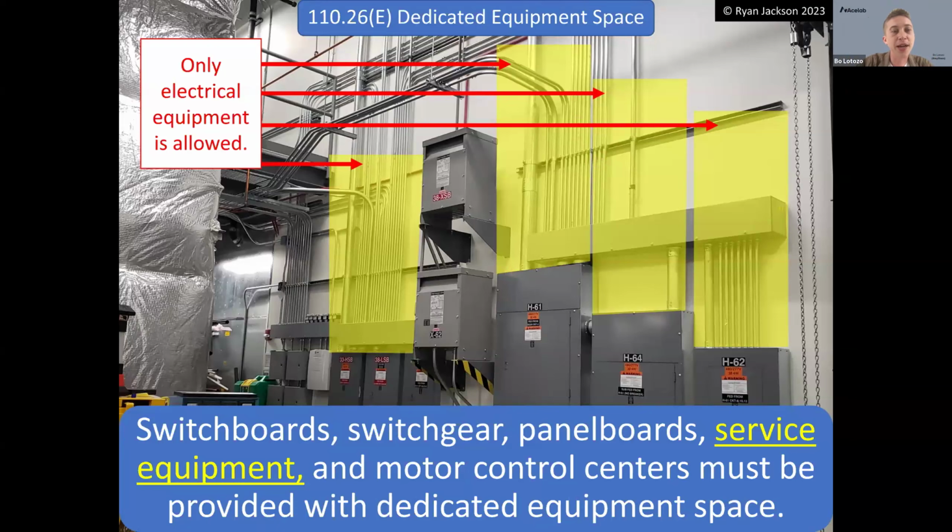All right. So Brian asks, what was discovered to be the culprit of the low voltage event shown in the early slide? Yeah, great question, Brian. So that was a low voltage lighting system, it was not what we would call Class 2, which is very, very low voltage. This was one of those lighting systems you sometimes see in restaurants where it has the 2 conductors that go through the ceiling, right? That are kind of parallel to each other, and the lights that hang off of them. It's a 25 amp transformer, and 24 volts is not enough to kill you with electric shock. 25 amps is enough I²R power to light the building on fire.